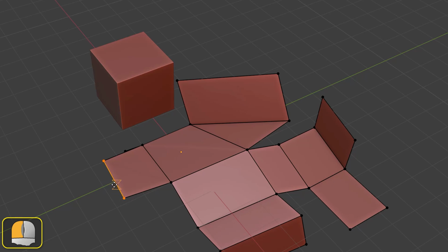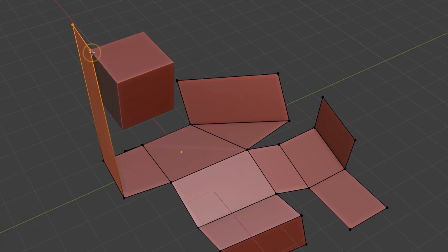A square for a vertex, triangle for the center of the edge, and an hourglass shape for the other parts of the edge. Next, we release the mouse over the element of the edge to be used for the snapping operation. And with no mouse buttons pressed, we move to the destination location. Again, we'll see the snapping positions here highlighted, and left-clicking completes the move.